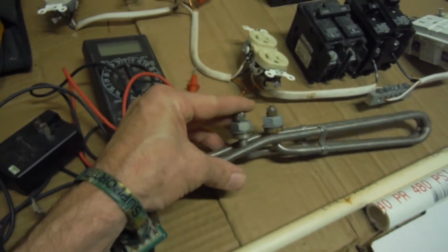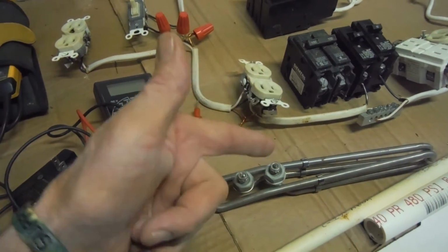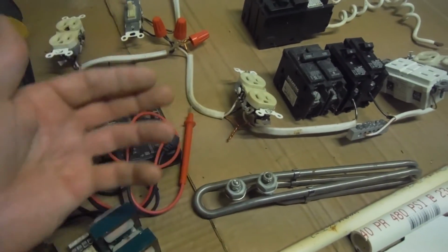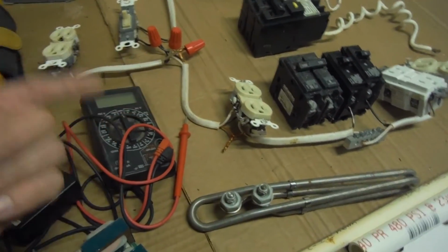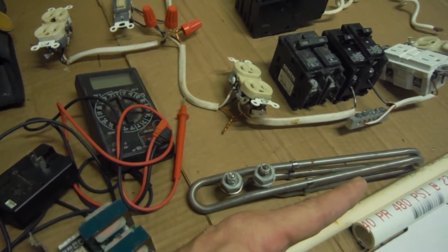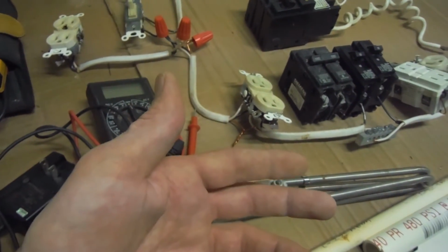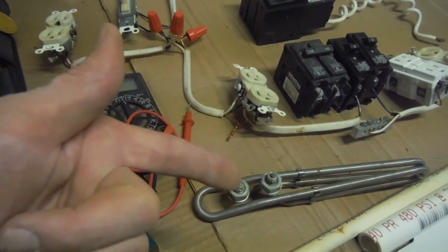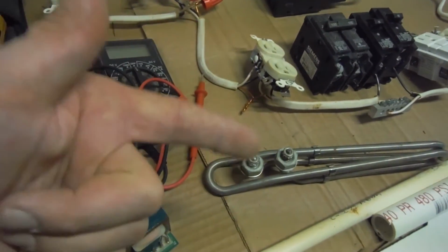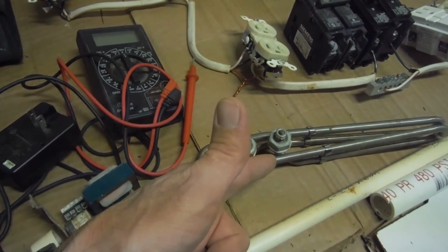For this heating element right here to actually work, first off, you have to have a temperature sensor that senses, hey, we don't have enough temperature, and a temperature sensor kicks on and kicks it in motion. That turns the pump on, which pushes water across this heating element here. That tells the flow sensor, or the flow switch, that it's actually getting water going across there, and it can actually apply power to this without having it burn right up.